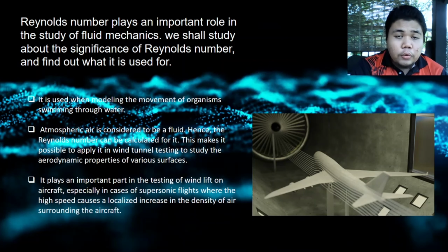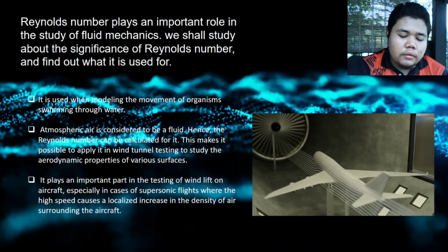So it means that the importance of Reynolds number is that it tells the type of flow we can expect. It tells you whether you can hope for having laminar flow over wing and other part of your airplane. A low Reynolds number gives a laminar flow, while a high Reynolds number gives a turbulent flow. For both laminar and turbulent boundary layer, increasing Reynolds number gives a lower skin friction drag. However, because of higher energy loss in the boundary layer, a turbulent layer always has higher skin friction drag.